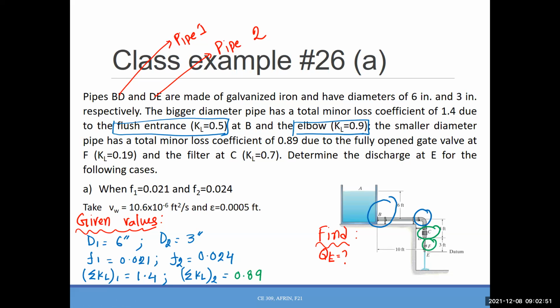Once we know that, it is about 20% of the problem solved, because that gives us two exclusive equations for this setup. We know the hydraulics of how the total flow and the total head loss are calculated for each type of pipe system, so it's important to identify the pipe connection. We'll start from that point for today's class.